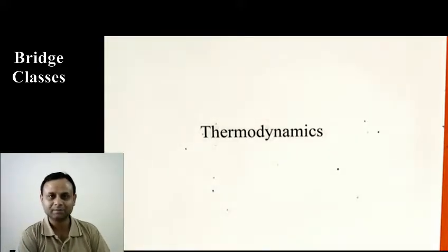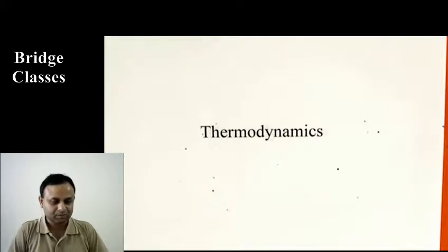But again, the main thing is, in general, if the substance is water or a refrigerant, you have to read properties from the table, from the subcooled liquid table or superheated vapor table. But there are special cases. One of those special cases is if the substance is incompressible. For an incompressible substance, we get all the simplifications we talked about: there is only one specific heat, delta U is C delta T, and similarly we have delta H also. So we can use that if we are dealing with liquids or solids. Okay, so there is a simplification.